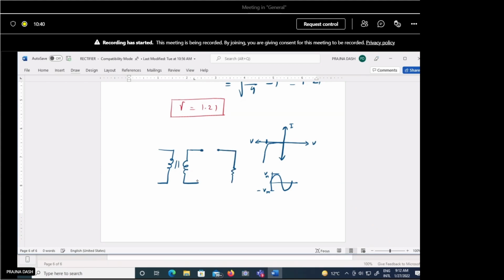That tells you the maximum voltage that can appear across the diode for a given input signal. According to the value of the input voltage, we should determine the maximum possible voltage across this open terminal. This voltage will give you the peak inverse voltage.